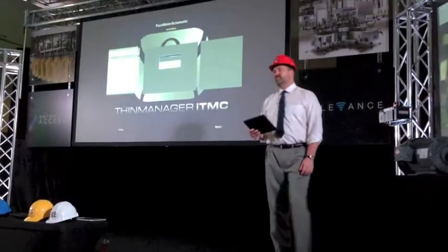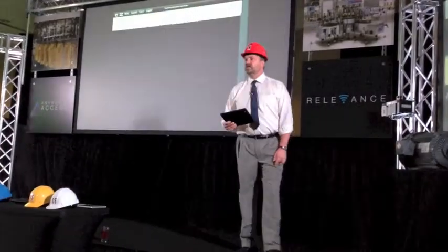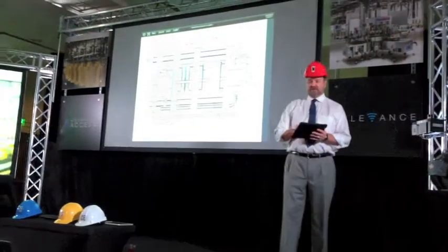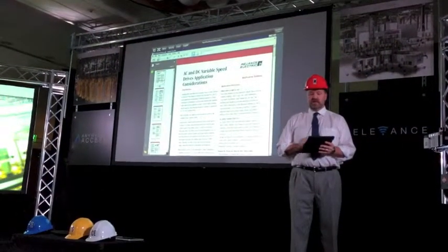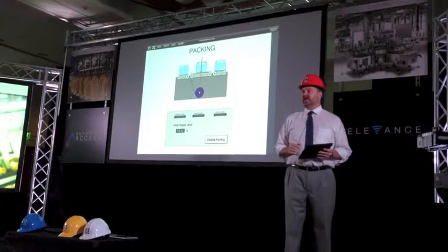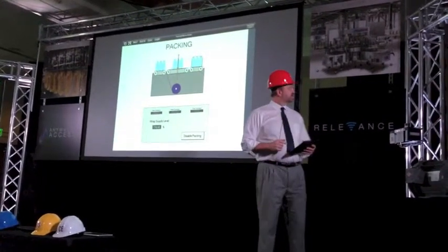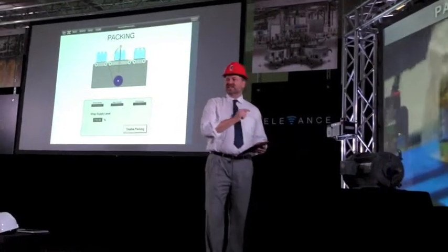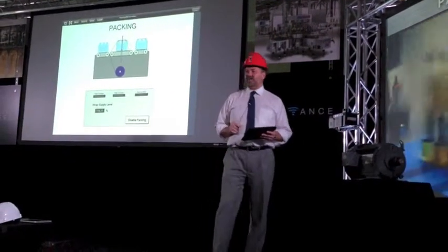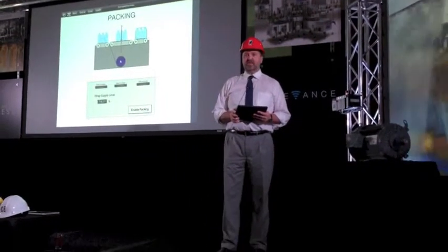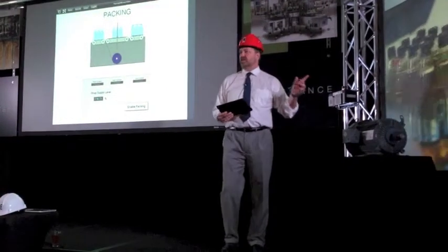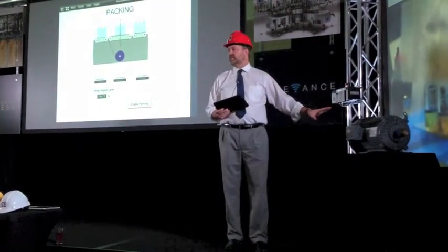And it's going to provide to me the content associated with that motor, which is the motor schematic, the drives manual, and of course I'm going to need the HMI if I make any changes. And I look at this and I say, that's a problem. I really need to fix this. First thing I'm going to do is I'm going to disable the packing line. So that process will stop, this motor will stop, and I'll be able to work on it, right?